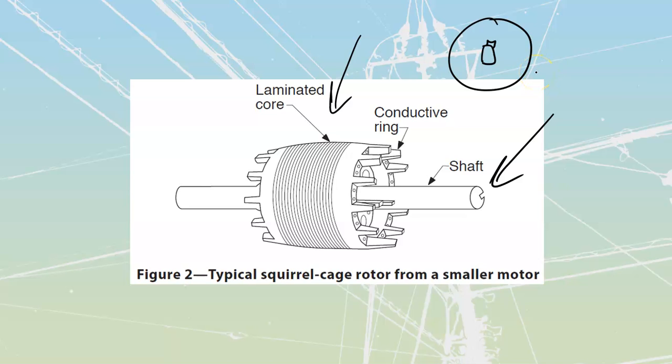They're going to be made out of steel so that I can magnetize it, because I do want to hold on to magnetic flux. We want to attract magnetic flux in from the stator, hold it into the rotor, and then carry it through the rotor and release it back out to the stator on the next pole. We'll cover all that stuff later on.